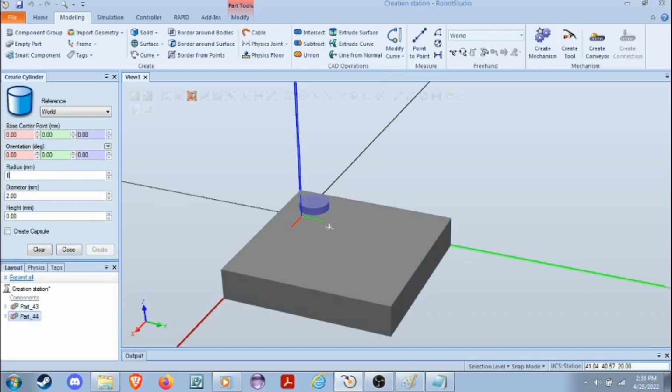So we're just going to continue making cylinders so that they peek out. This one's going to have an x offset of 20 and a y offset of 55, along with a z offset of 10. This will create the next one. Moving forward, we'll do 20, 90, and 10. This is so that we have an x and y offset of 35. As we're going through, we're going to adjust the x and y offset, or if we had different pallet shapes, we can change the x and y offsets. But for this example, we're going to go through and continue making all the cylinders.